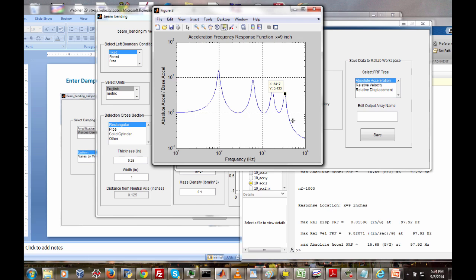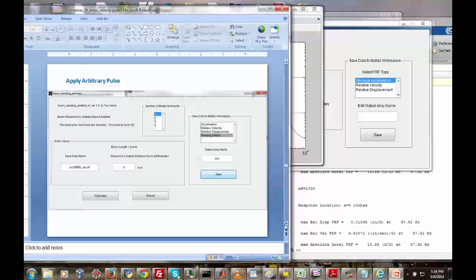This is about 3.4. But what we could do is the half-power bandwidth method. And if we do the half-power bandwidth method, we would in fact get a Q equal to 10 for each of those four spectral peaks. So the point is, this being a continuous system, and this is true for multi-degree of freedom systems as well, if we want the Q value, we cannot pick off the peak value at each of the four resonances. Rather, we have to use the half-power bandwidth method. And let me see what the slides have us do next.